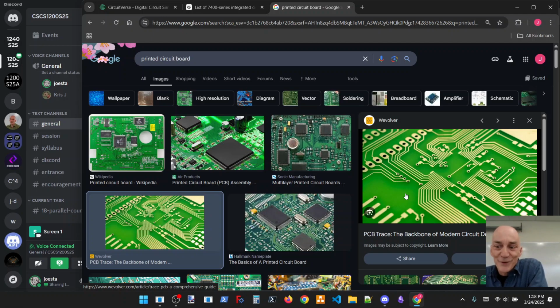For most common applications, there's some weird materials when we get into high frequency stuff, but it would typically be literally a fiberglass material sheet, and you could get it coated on one or both sides with copper. So a thin layer of copper that would be either deposited on, in other words, evaporated and condensed and deposited onto the board, or rolled onto the board.